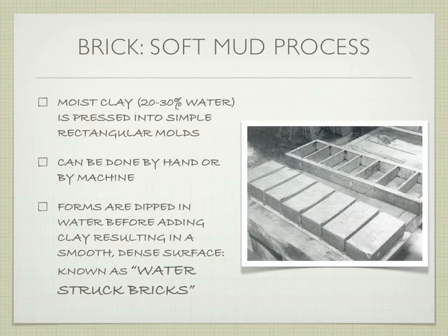So if you look at something like this, which, since I only have one that's a good example of it, I keep walking back here. But if we look at the face of the brick here, it's a very different smoothness than the edge. The edge is what we're going to see when it's in the final building. So this is the part that's water struck, because it's that smoother piece. So I might as well pass this one around. I'll start holding a different brick, and you guys can see that one. Okay, I can hold this one for now.